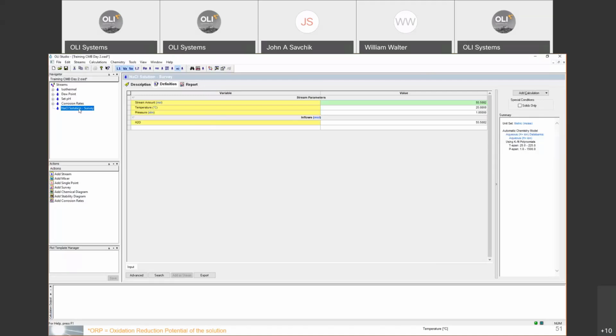And for this calculation, I want to use the MSE framework. So we go to MSE, okay? Let's select this MSE button up here. And we will see that our thermodynamic framework has changed to MSE. Let's change the units as well. So while selecting this sodium chloride solution survey, let's go to the units manager. Just click on that units manager.